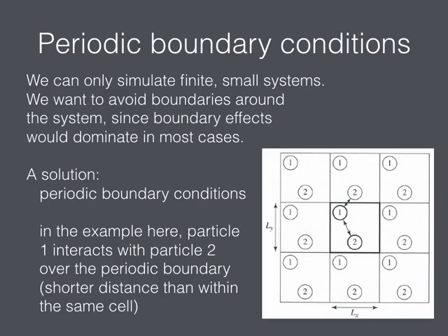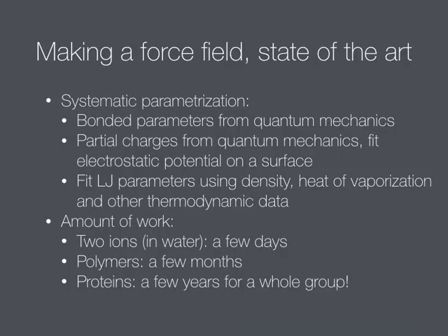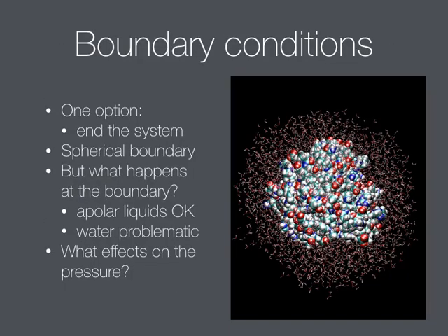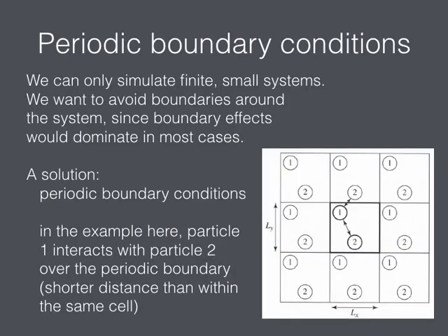One trick is periodic boundary conditions. So you could simulate a protein in a solvent shell like this, which some people still do, although that's a very old-fashioned setup. What you get then, if you would just have vacuum outside this, is a high surface tension on this edge because you get a droplet. So you get surface artifacts. Also, the electrostatic interactions would be strange, because you would get an electrostatic or dielectric boundary here at the edge. So to avoid such things, the simple trick is to use periodic boundary conditions, which is a Pac-Man-like thing.